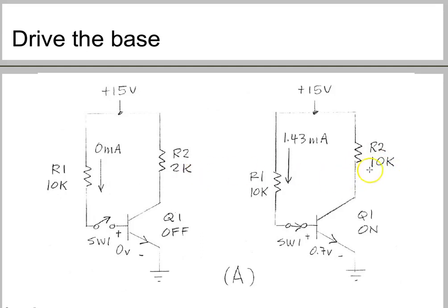So this is 2 kilo ohm, this is 2 kilo ohm. So now simply stated, when base current is turned on, the transistor is turned on, and when base current is off, the transistor will be off. So by this example, we'll see, like in the first method, how to control the base current of the NPN transistor. This is the NPN transistor. Current is going outside to the emitter side.